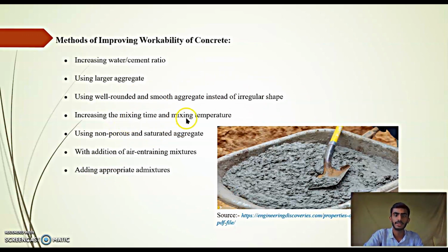Increasing the mixing time and mixing temperature. As the mixing time increases, the workability also increases. Therefore, mixed proportions get mixed easily, and using non-porous and saturated aggregate. Next is addition of air entraining admixtures. We learned that admixtures also play a vital role in increasing the workability of concrete. Therefore, adding accelerators accelerates the strength of the concrete and also the flowing fluidity of the concrete. Then next